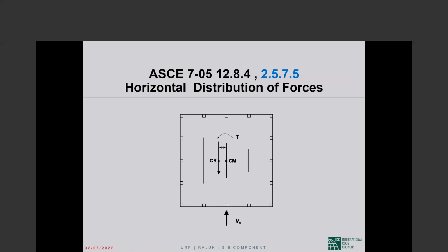The shear walls and columns account for very little of the mass. So the fact that the left shear wall is so much longer than the right shear wall does not move the center of mass all that much to the left of the centroid.